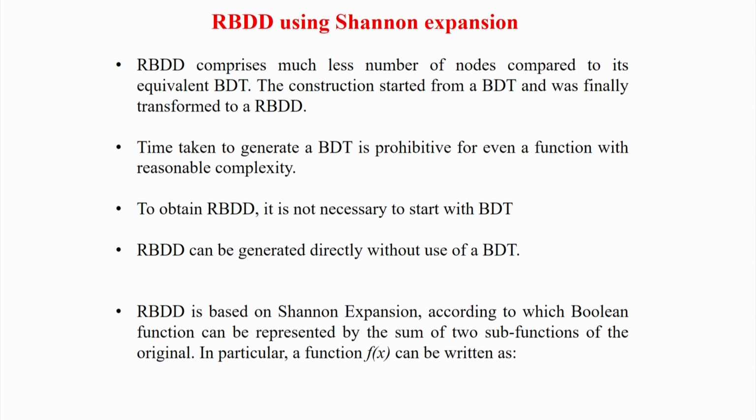It should always come to your mind that if you have the binary decision diagram or binary decision tree, then we are using a lot of elimination etc. to do it. But the binary decision tree itself is not available for a very large circuit. Then how can you make the binary decision diagram? Because you have a very big structure, you are reducing it and making a binary decision diagram. But how to make the big tree itself, that is a very big question. The idea is that nobody actually does it in that fashion.